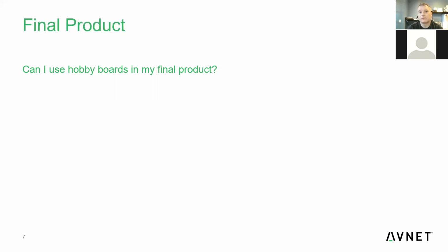So usually we want to avoid those connectors, and most of these hobby boards have tons of connectors on them to make them easy to use. There's a ton of reasons I could go over for not using them. In some cases it might make sense, in some cases it doesn't, but I would say in the majority of them, it does not make sense. And you should be, right from the beginning of your product, considering when you're going to move to a custom assembly or board.